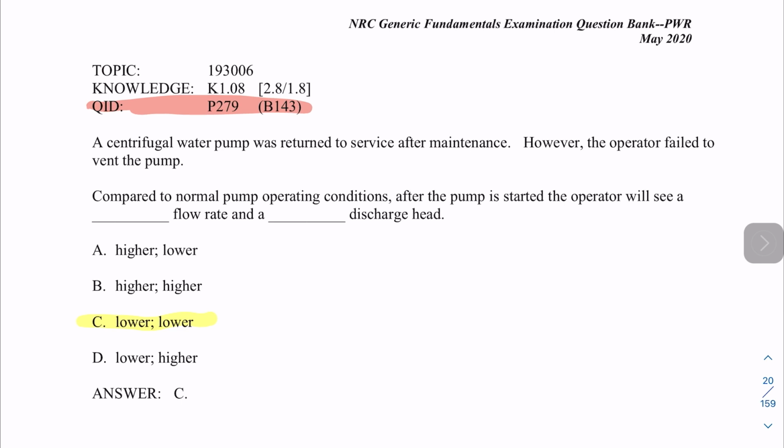That's why we need to make sure that we vent the system, the pumps, prior to operation, so we can make sure that all the air that is trapped there is removed. Because the water will be displaced by this air that is trapped, and therefore it will reduce the pump capacity.